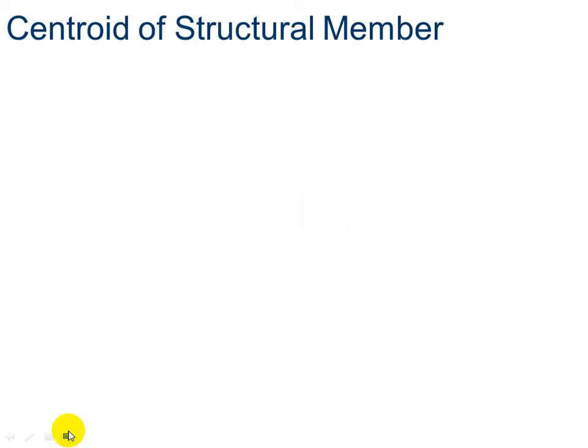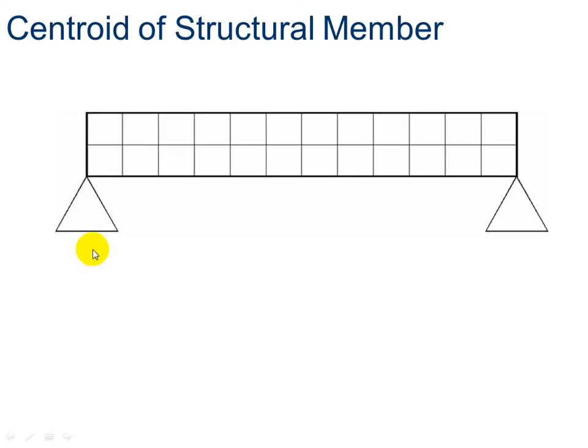The reason centroids are so important for us is because when we're discussing the forces acting on a bridge and forces acting on something in statics, we always draw the forces acting at the center of the mass or the centroid. So when we're talking about bridges and the like, we always need to know where the centroid of this member is, because that's where the force is going to act.